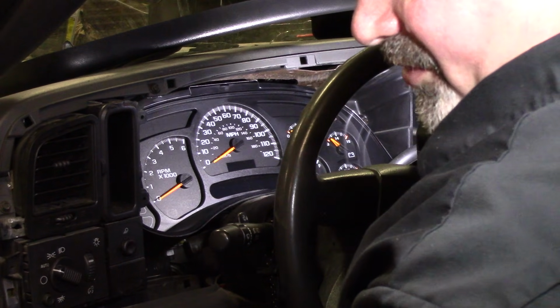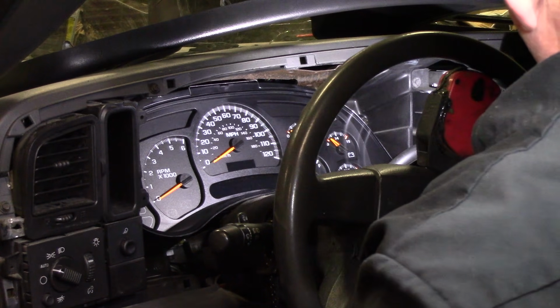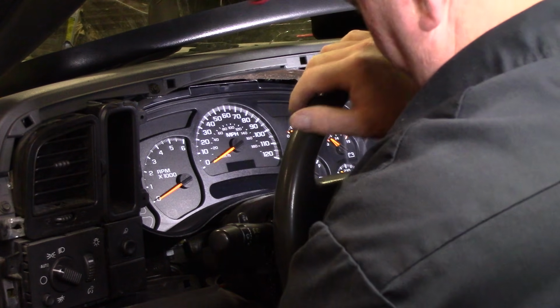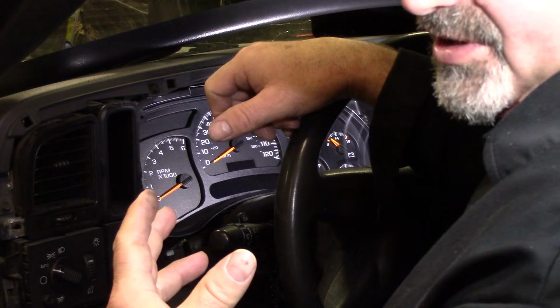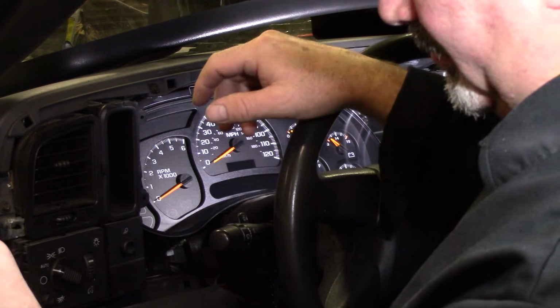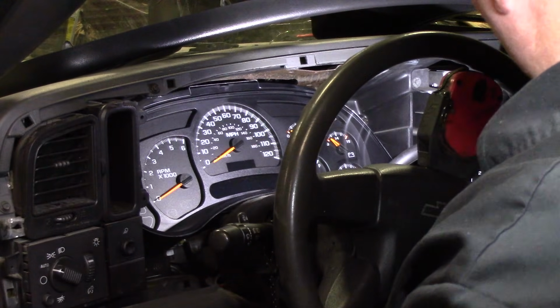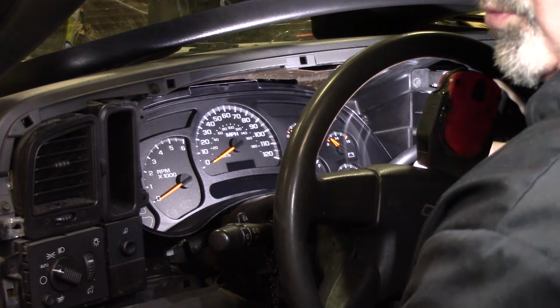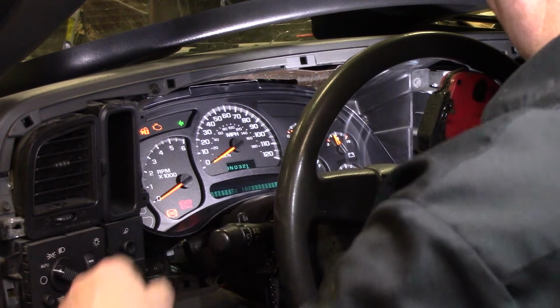Forgot to mention one thing you might try if all these tests have failed to produce any results. Do a hard reset: disconnect the battery, wait 30 seconds, touch the cables together, and reconnect it. Sometimes resetting the module will bring it back to life as well.